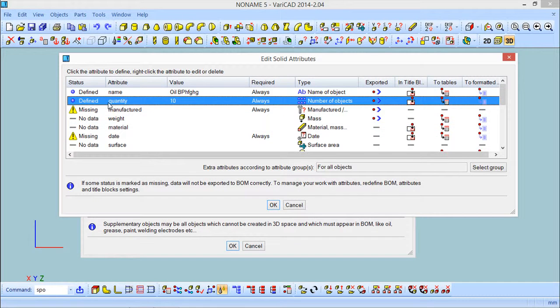But the idea is to define these kinds of objects that cannot be modeled, and when you have that definition done, the purpose is to insert them in the bill of materials, and besides the solids we have, we can insert also these objects we cannot see on the CAD system. I'll try to show you after the configuration of the bill of materials, and we try to create one or two objects to show you what it is possible to do.